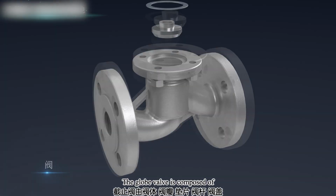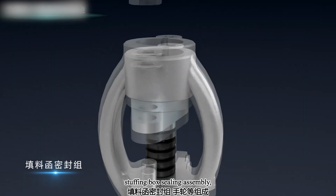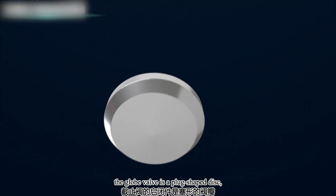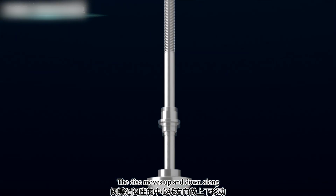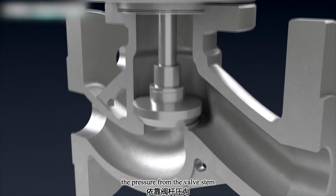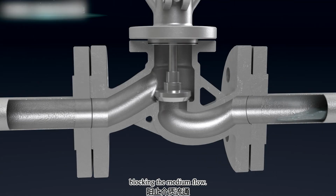The globe valve is composed of the valve body, disc, gasket, valve stem, bonnet, stuffing box sealing assembly, hand wheel, and so on. The opening and closing member of the globe valve is a plug-shaped disc, with the sealing surface being planar or conical. The disc moves up and down along the central line of the valve seat. When closing, the pressure from the valve stem makes the sealing surface of the disc closely fit with that of the valve seat, blocking the medium flow.